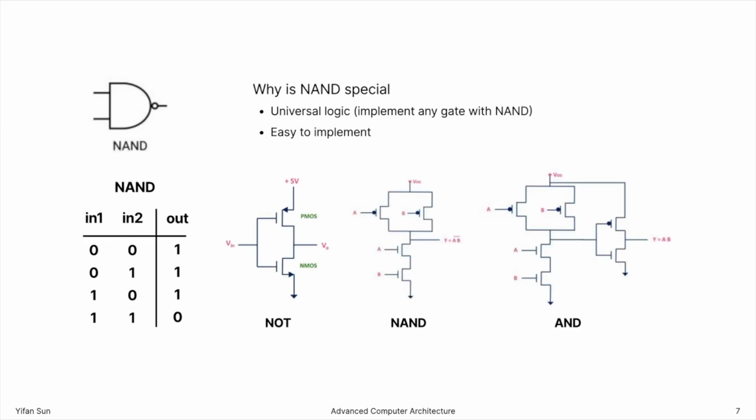Then you see there's a small circle that means NOT. So NAND means we first do an AND operation, then we take a NOT of the result. And for OR, NOR is the same thing. We first calculate an OR operation, then flip the result. XOR, we have talked about that before. It's represented by the extra line behind the OR gate. Then XNOR: we flip the result of an XOR gate.